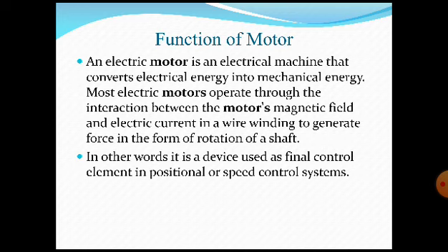Okay, and basically these drives or the motors are used for providing the motion to the workpiece, cutting tool, or the work table. But the work table is not rotated. The work table is always made to move in a linear direction. So for that we require a certain mechanism through which it is possible to convert the rotary motion of the motor into linear movement of the table. That we are also going to discuss in the subsequent presentations.